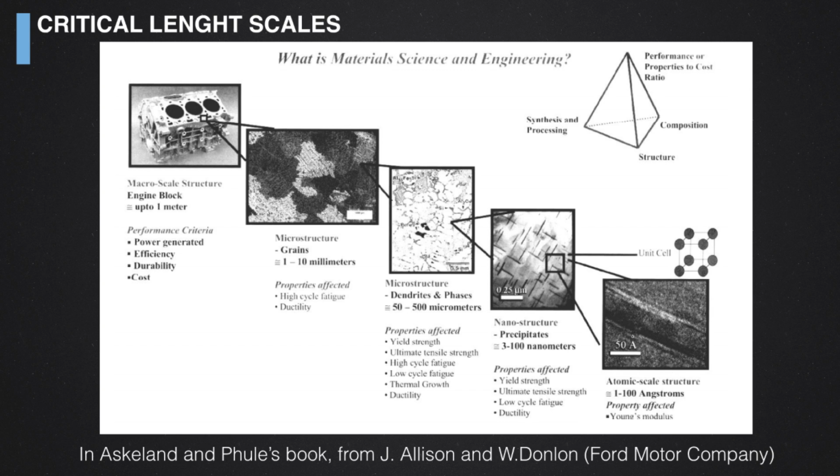Outside this coherence zone, there is the so-called grain boundary, where the atoms are disordered and in a glassy structure. A macroscopic structure normally has a polycrystalline definition, meaning that we have many different grains, each one is oriented in a certain way.